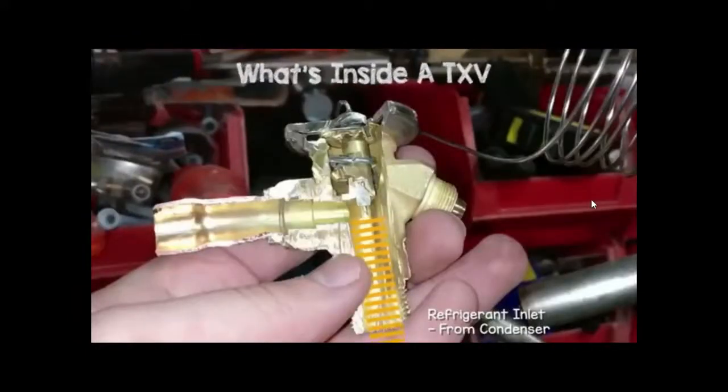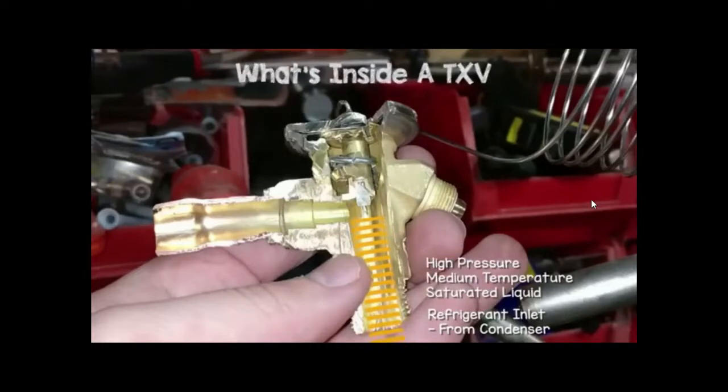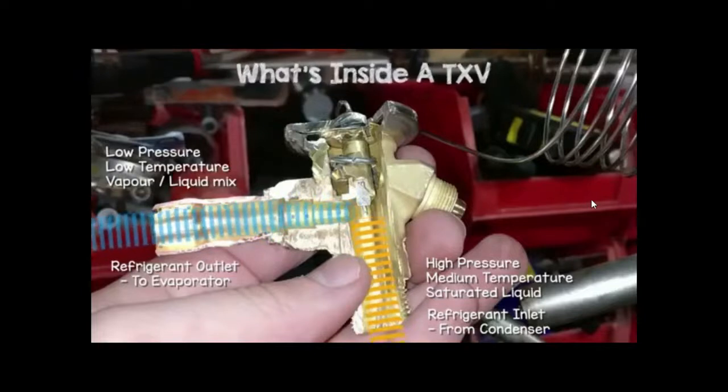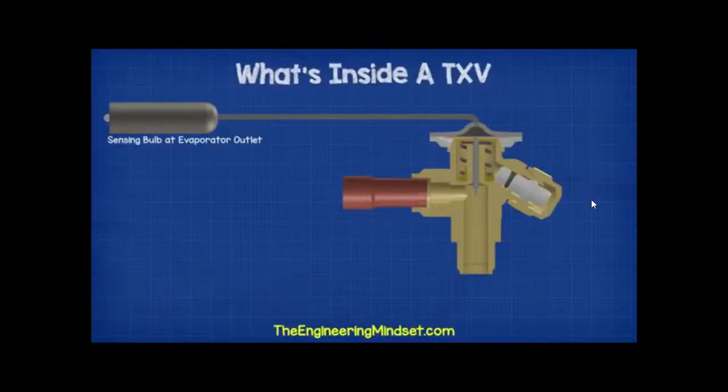So the refrigerant comes from the condenser and enters the valve body via the inlet. It enters as a high pressure, medium temperature saturated liquid. It then passes through the valve body, and when it leaves, it exits the valve through the outlet and will now be a low pressure, low temperature liquid vapor mixture. So what's causing the change in pressure, temperature, phase and also controlling the flow of refrigerant?